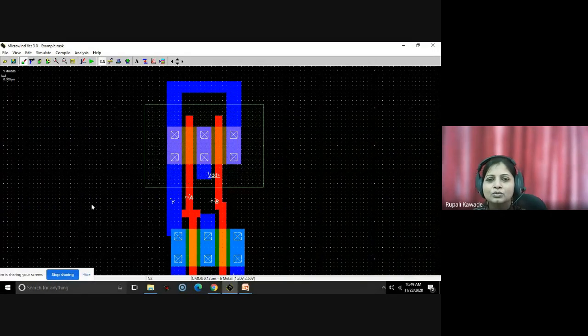Okay, so it is expected to draw the CMOS combinational design, its respective stick diagram and the layout. Fine. Again, the very important thing is, now we have drawn here a layout, so I can take a length or the width for these layers. What should be the distance or spacing between the diffusions? It has rules. Those rules you can define, whether this circuit is violating the rules or not.